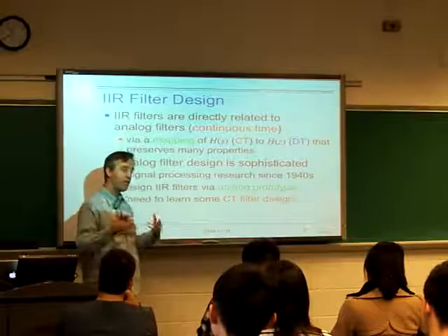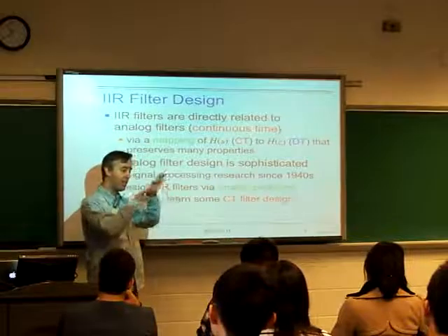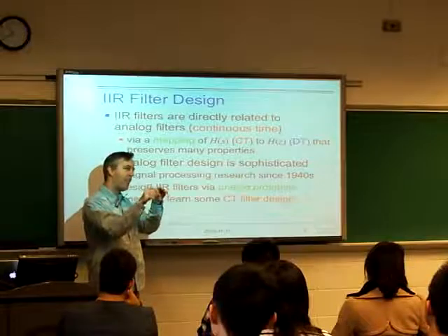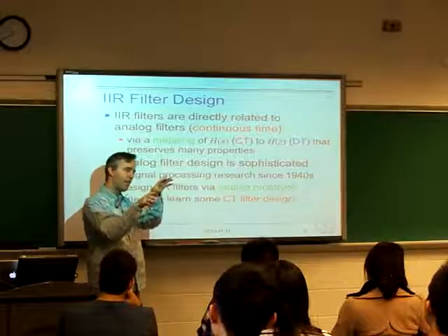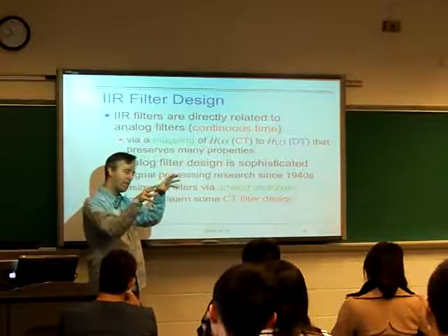You can do something similar in FIR, but you've only got zeros, so what you have to do then is put the zeros everywhere except where you want the frequency to go through. And then it becomes much less obvious how the actual behavior in the pass band depends on the exact positions of all these zeros.